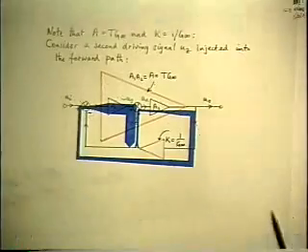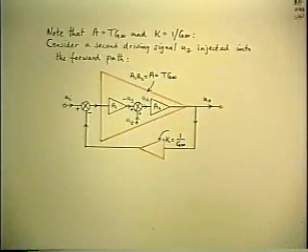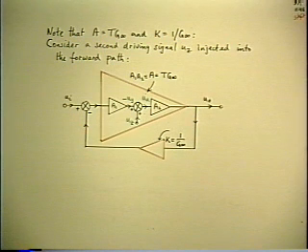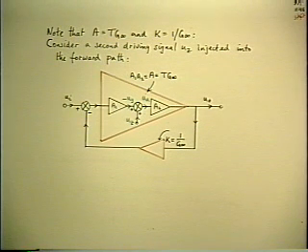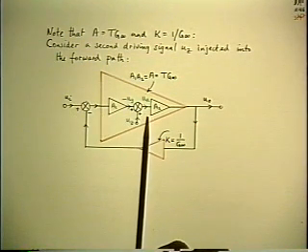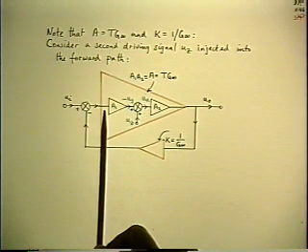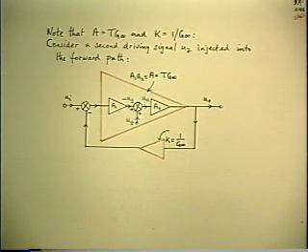You can extend that same process to find the G infinity. To find the G infinity, let's think a moment about what setup you could use. G infinity is the ideal closed loop gain if the error signal is 0. How can you establish a set of signal conditions in order that you can make the error signal 0? Null double injection.